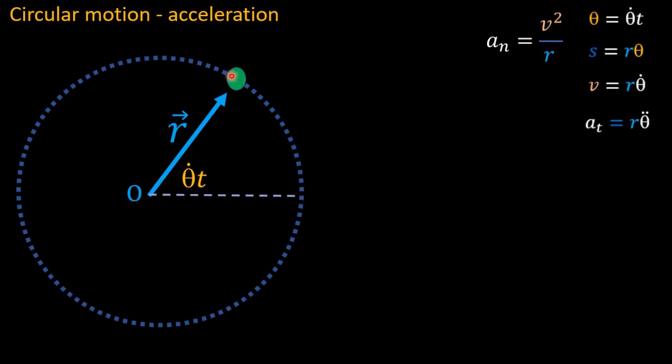As the particle moves along that curve, theta is going to increase, and it increases with time. So as time goes on, the angle is going to increase, but theta dot is going to stay constant. So I can define the particle's position at this point as a horizontal distance, which I'm calling r times cos theta dot times t. So I'm just using r cos theta, but I've just substituted theta with theta dot times t. Okay, so that's its horizontal distance here. And then I can define the vertical distance as r sine theta dot times t. Okay, so I've just defined its position.